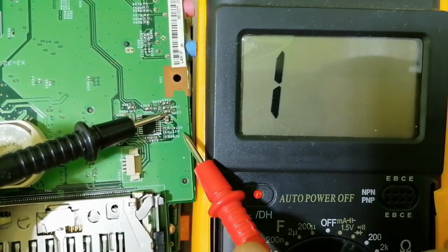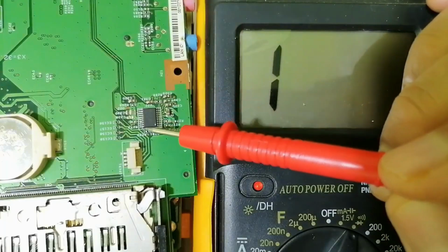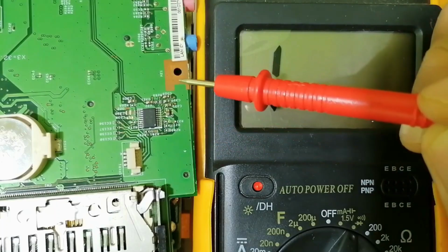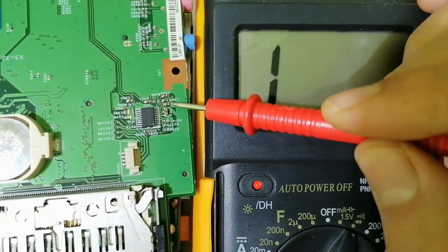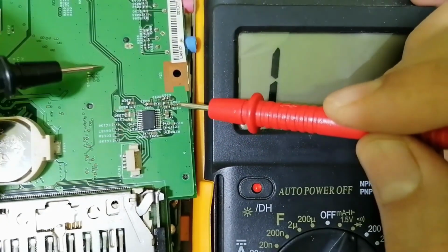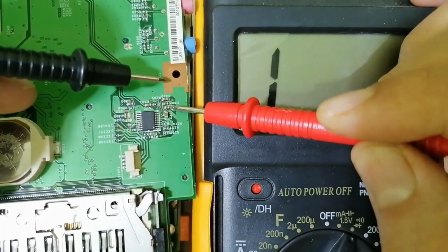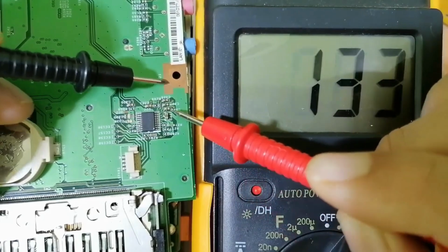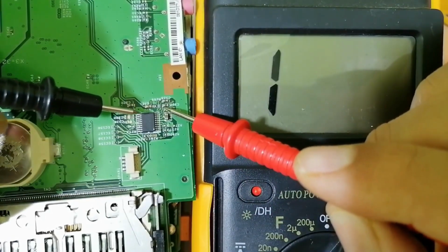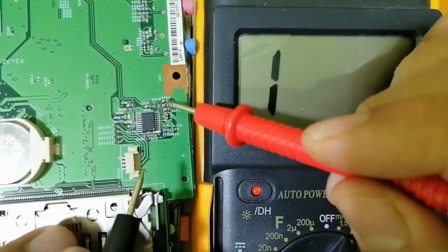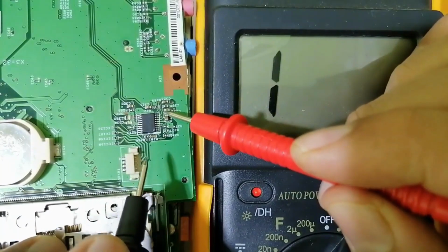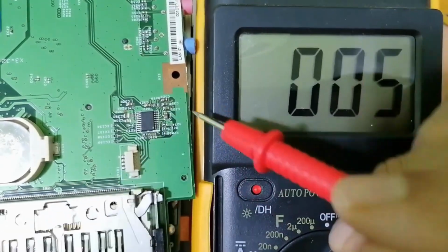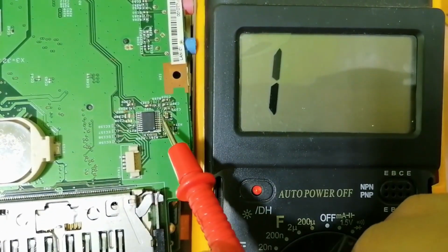This is ground basically. So all capacitors around the IC, you will find connected to the IC on one side and to the ground on the other side. Let's check this one for example. This ceramic capacitor also, as you can see, this pin is connected to the ground in this terminal, and this terminal of this capacitor is connected to the IC over here, as you can see. Do you see the path? Here we have the path.